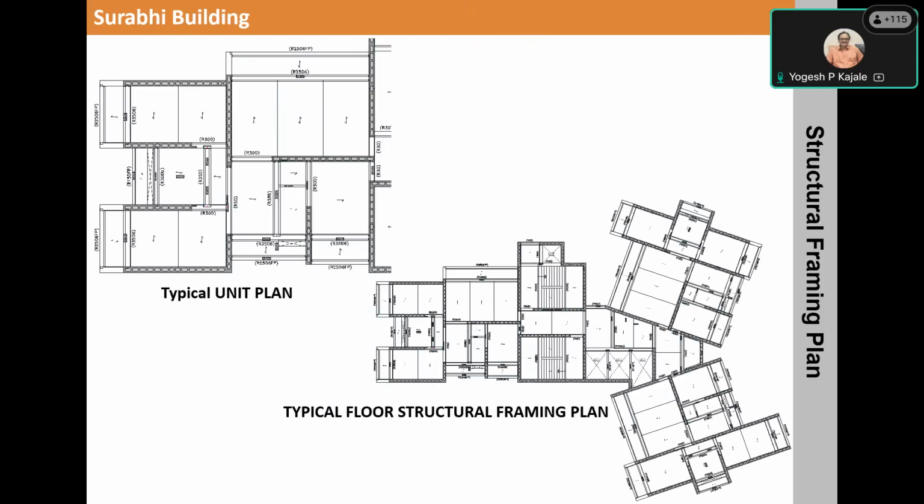There were restrictions on the turning radius of the trailer, and a lot of restrictions in terms of transporting such heavyweight components within the city. So the component planning was done in such a manner that the crane capacity is optimum and the components can be transported long distance, with minimum wastage or breakages, rather almost nil, during transportation.